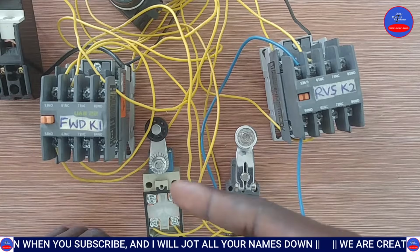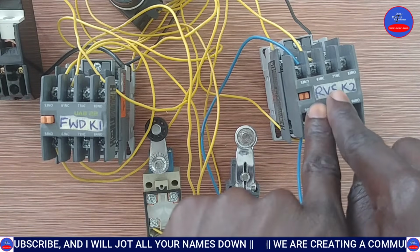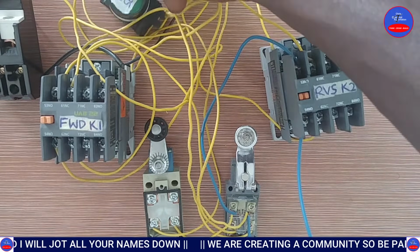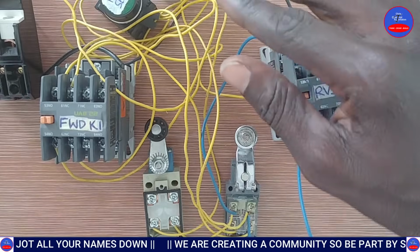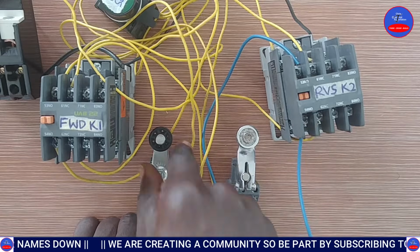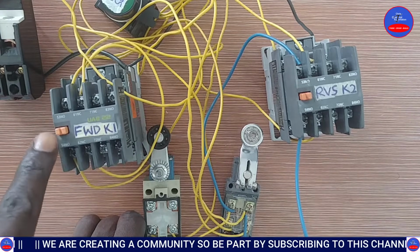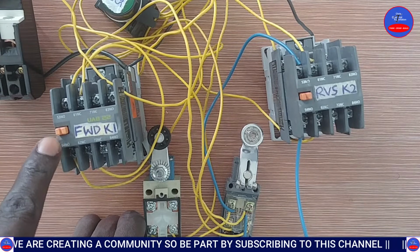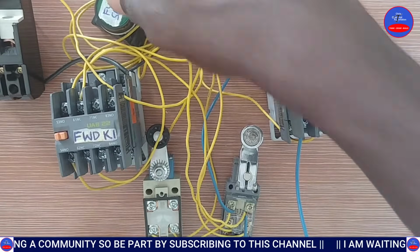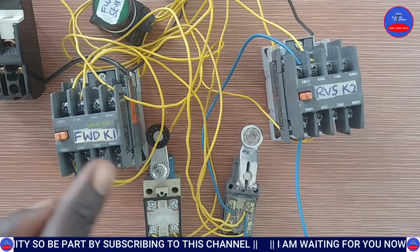But this time, when it hits limit switch 1, this one would de-energize, but K1 will never come on unless we press the forward push button again. So as it hits it, see that it has gone off, but K1 didn't energize unless we press the start button again. So when you press the start push button, it will move this way.